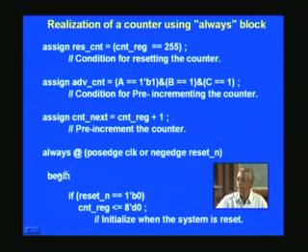And once again, we see begin and final end in an always block, and at positive edge of clock or negative edge of reset. These are all the standard things. As I said, it will keep on recurring later on. And if reset is asserted, this also you have already seen. The only difference is this counter register, which is 8-bit, is reset to 0 value.